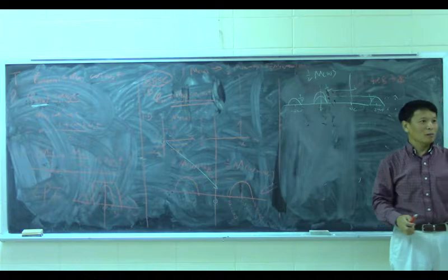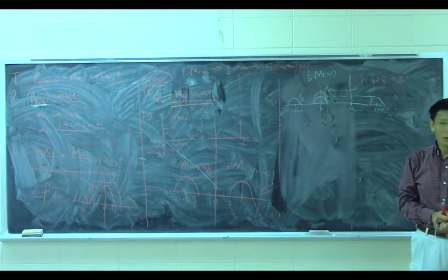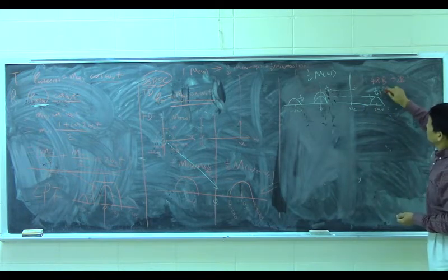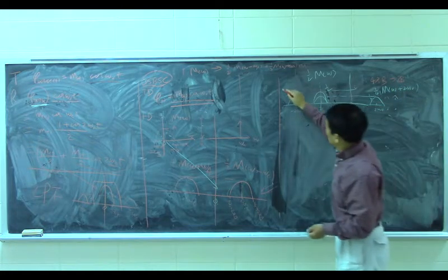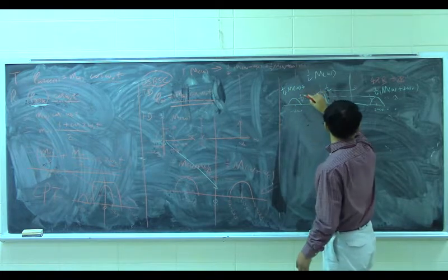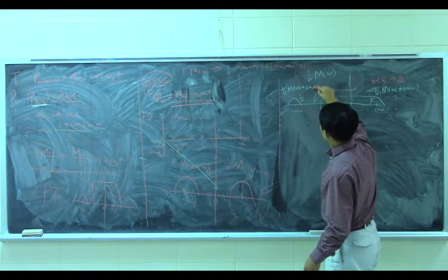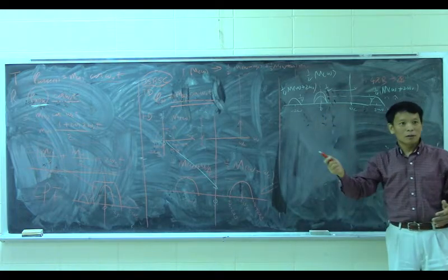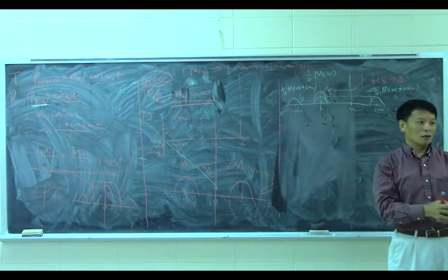You have a lot of amplifiers. You can boost this one to 1 or 10. That's no big deal. This one equals a half. This one equals a quarter. So that will be M(omega plus 2 omega c). And this one will be a quarter M(omega minus 2 omega c). This one will be minus, this one will be plus 2 omega c. Right? So that is the spectrum of the received signal multiplied by cosine omega c t.